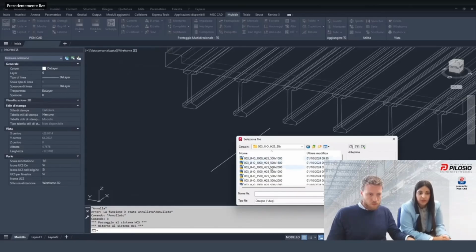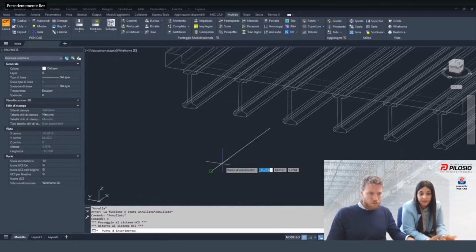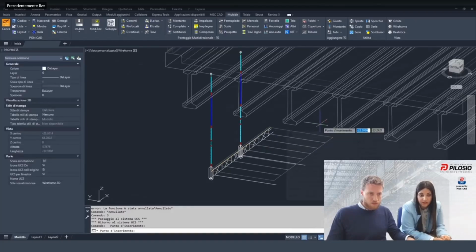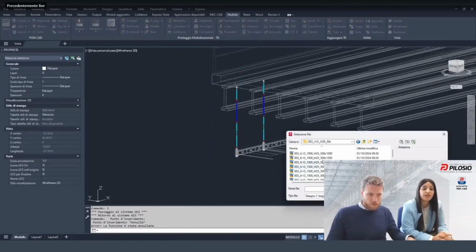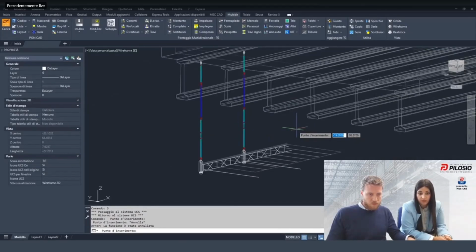In our library usually you can find some steps already erected with the beam, the panel, the transoms and the chains. Usually we start with a 4-meter beam because it's more handleable and easier to erect. And then with the help of the fly rail, we erect the 6-meter beam.